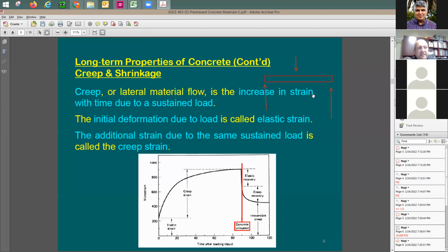But if you leave this point load, let's say for a year, this phenomenon, which is called creep, is going to happen. You're going to see here more deflection because the molecules and the particles within the concrete itself are going to start to move, and more deflection is going to happen. So we're going to call this long-term effect, and this is what you call here the creep. So the creep is going to be this inelastic displacement that happened in the beam.